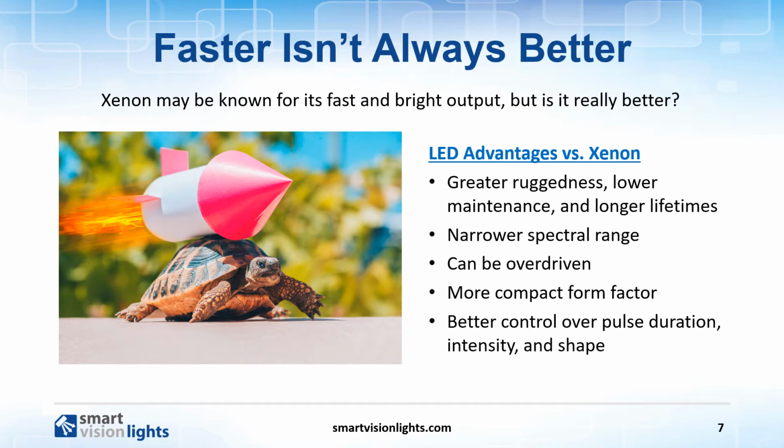This is very important in machine vision because the absolute intensity of a light at its source has less bearing on image capture than the flux density created at the target, the number of photons per unit area projected within the target field of view per 1 second of time. The key is not the absolute intensity of the light source, but how many photons it can deliver to the target some distance away.